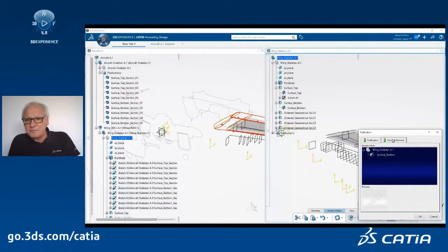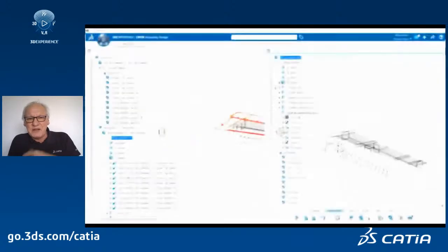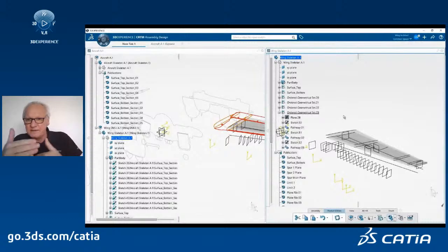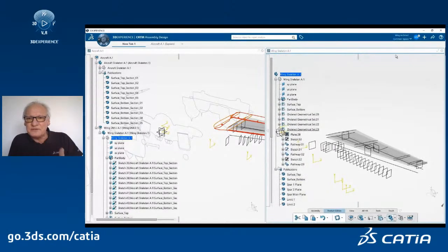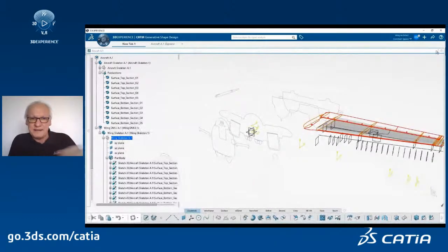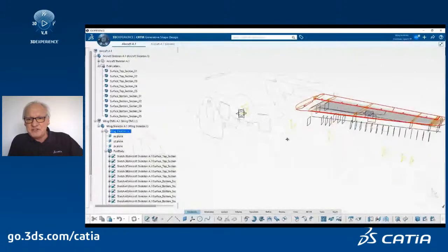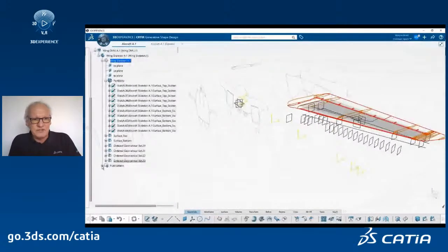You can see what are the pointed elements. What is the pointed element in this particular case? I will add other information like the spar planes. There are two spar planes. There is a main one, some limits. So you see, I define which is relevant to my design to perfectly control what will be passed to the downstream processes of designing the detail of the individual parts of my wings. Okay, that's my job, almost finished. This is all my publication. I'm fine.